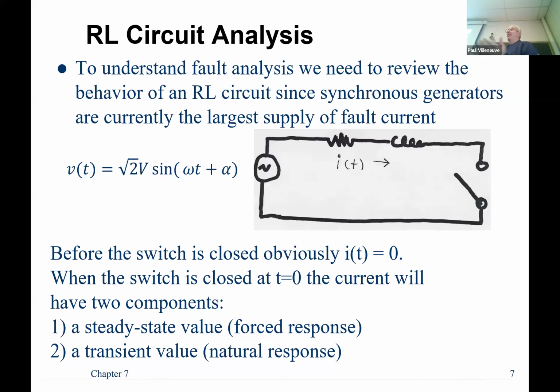There are devices like a motor, an air compressor, or an HVAC system. Those things are cycling on and off all the time, right? So they have what's called a contactor that opens and closes, just like our switch, maybe millions of times. But that's just opening and closing a small amount of current. If a fault occurs and that contactor tries to open during a fault, it's going to damage the contactor.